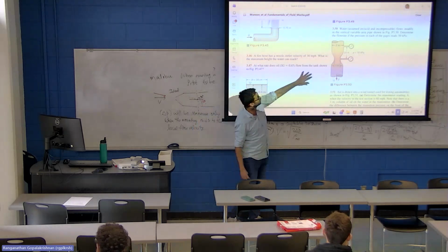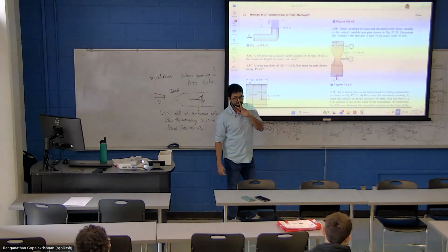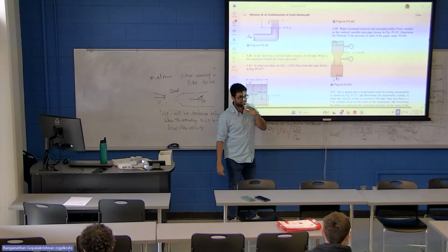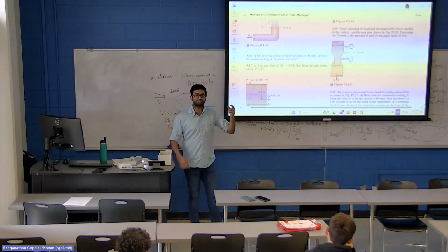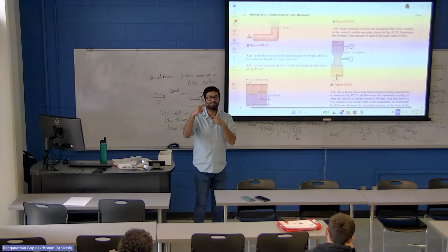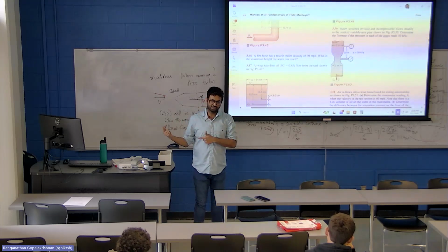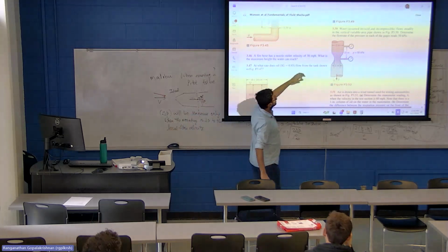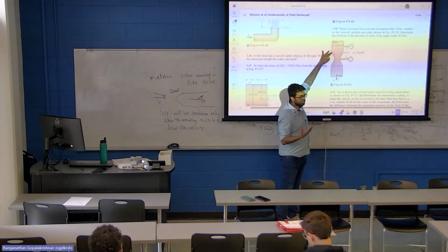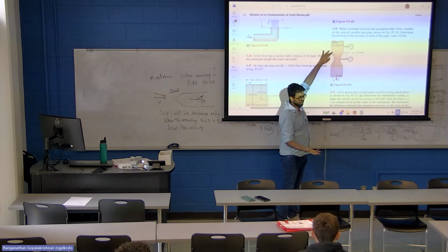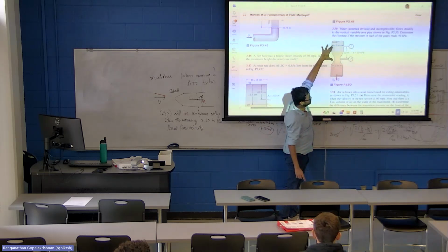The cross sections with pressure gauges, because that's the only place, only 2 points, where you can actually apply Bernoulli knowing the pressure. If it were anywhere else, say some midpoint between the 2 gauges, it's useless because you don't know the pressure there. So the points of interest are the sections with the gauges.